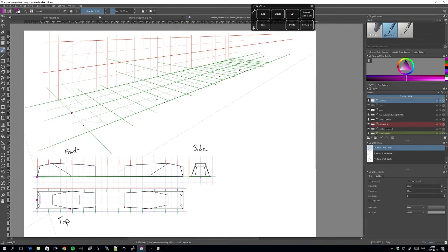And the last point is, let's see here, 5, 6, 7, 8, 9, 10, 11, 12.5. So that line over there, that's 12.5. That's the end of the sleeper. And this point is supposed to be in line with that point towards the vanishing point. Great. So now if you just take a line tool, you can actually connect the dots.